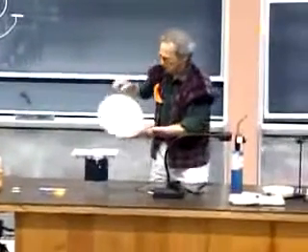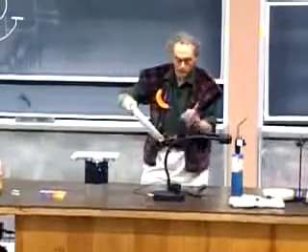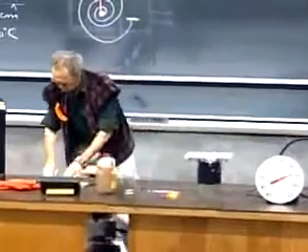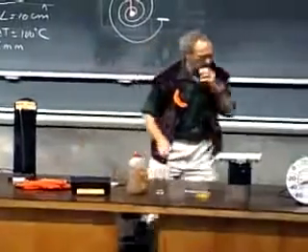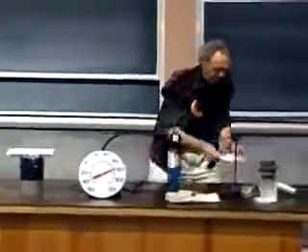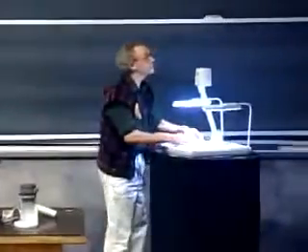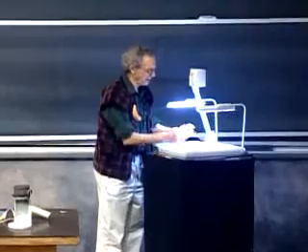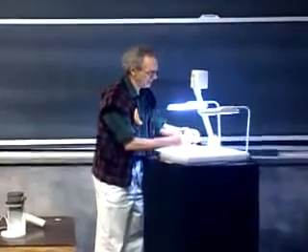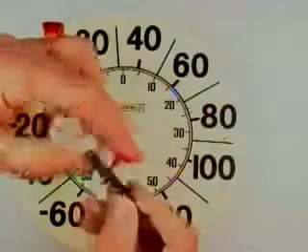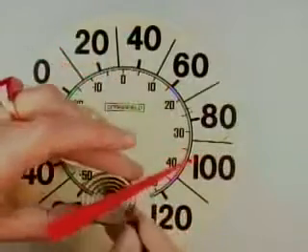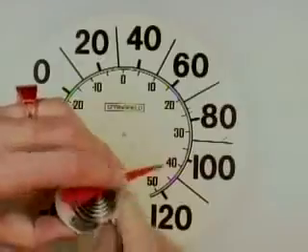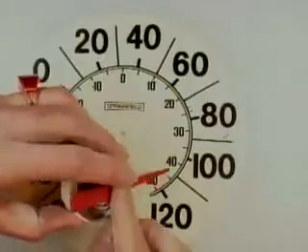And in the back is this coil. And so I broke one open for you in order to make you see that coil. So I have that here. This is the part that is in the back, and this is that bimetal, the bimetal coil. This is the bottom part, this is the top, and this is just the hand that is attached to it. And then it goes into this case. Let's make sure that the pivot goes in there.